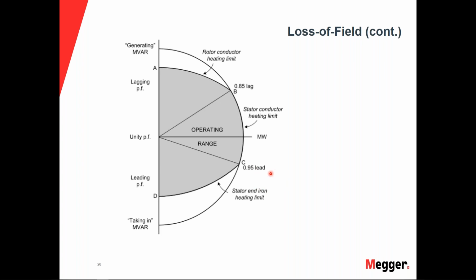So we want to give it some type of protection parameters that allow us to trip it offline if we are in a scenario where we're losing the generator itself. We want to make sure we're tripping it offline as quickly as possible. We don't want to drag down the rest of the system, and that way we can look at what's happening to this local generator that we're having issues with and try to get it back up and online.